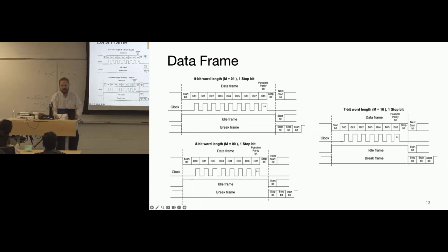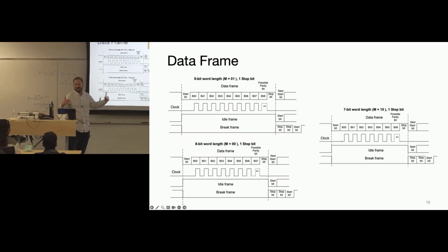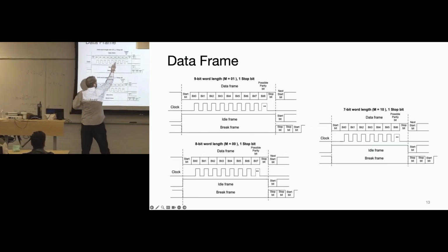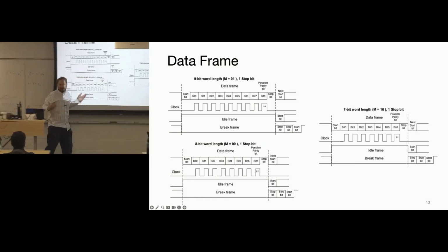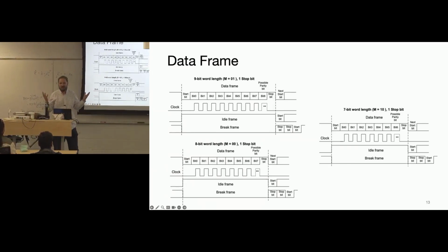Your computer, you're using Hyperterm or some terminal that the lab gave you. You have UART and you set it to something, and then you thought for sure you set your microcontroller to something, and those two baud rates don't match, and now you get gibberish. You still might get ASCII characters out. It might look like something because it still sampled something, even though it was at the wrong time. And then you get some weird ASCII character you've never seen in your life, and then you're trying to debug that for an hour. That's the first layer of UART problems.